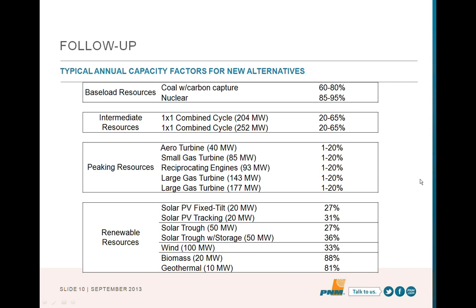So I don't have a number to give you for that. On the other hand, what we do know, and it's fairly easy to observe just from looking at data, is that the wind can go from 0 to full output in a really fast period of time. So those are the kind of things that are easier to understand and quantify: in order to keep the system reliable, we have to be able to predict that that's going to happen. We have to have resources on the system that can spin up very quickly to get to a good level of generation so we can balance those dynamic changes quickly.